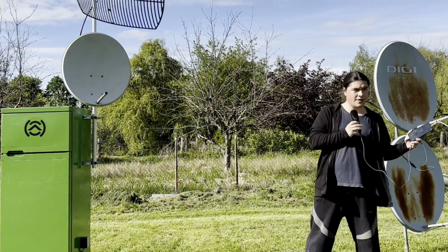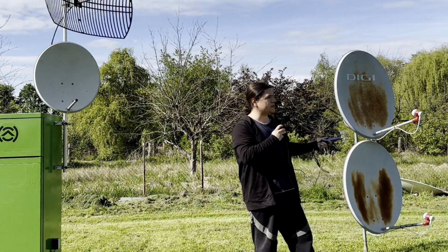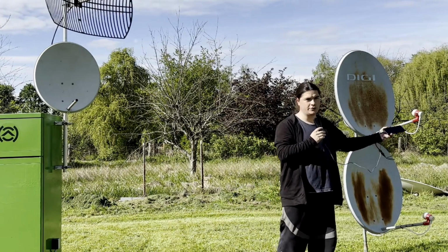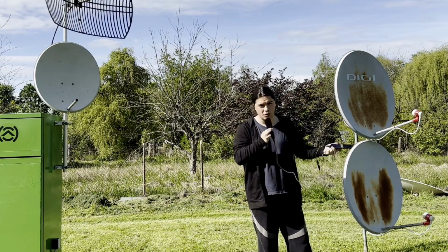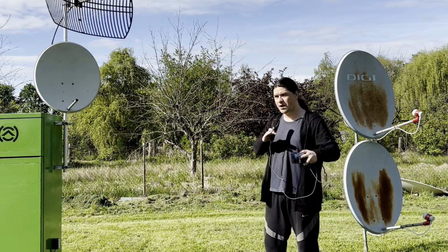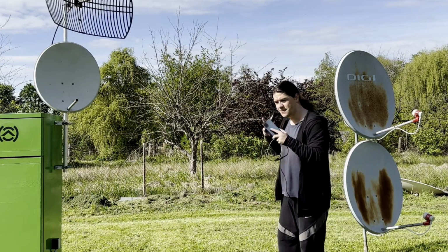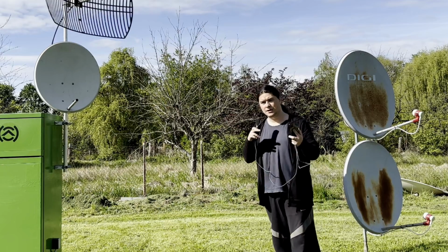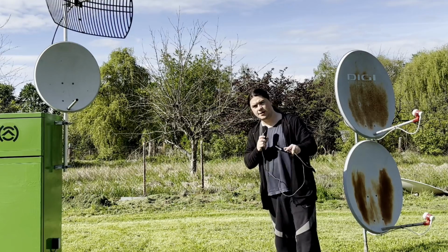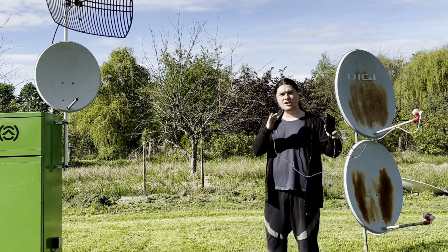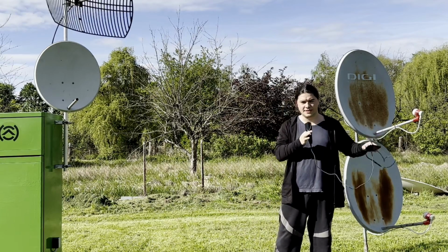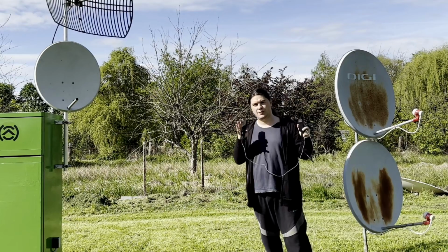The LNB without any frequency compensation can be quite a bit off, which means the local oscillator is not going to be exactly as advertised, and that's normal. That usually doesn't matter at all with satellite TV signals that are multiple megahertz wide, but with this, it actually does matter. So what I suggest you do is, when you are first looking for a satellite, set your SDR to at least 2 million samples per second, just in case the LNB's local oscillator value has drifted that far from its intended frequency. It's better to look with a wider bandwidth.